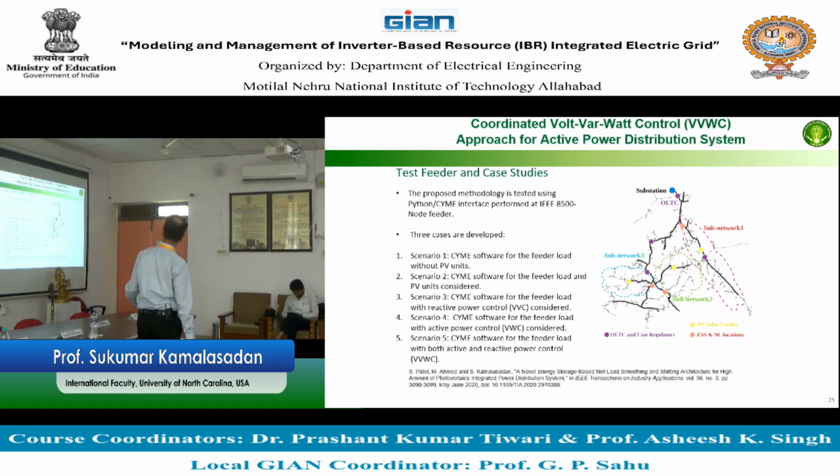In one of these works, what we tried to do was this: the duck curve is in the generating station, by the way, because generators see the duck curve. So we thought of an idea: this duck curve is coming from all the renewables coming in there. Can you make this duck curve local? We call it a local duck curve. So many of these small duck curves add up to this big one which is seen by the generator.